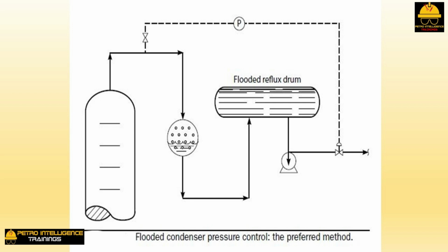The function of the reflux drum in a flooded condenser design is to separate water from reflux when distilling hydrocarbons, give the operators time to respond if they have exceeded the condenser's capacity, and provide a place from which non-condensable vapors may be vented.